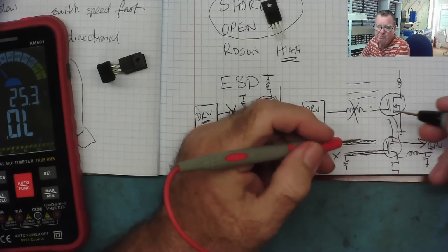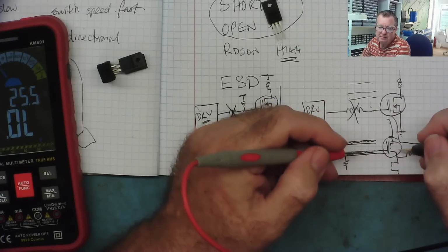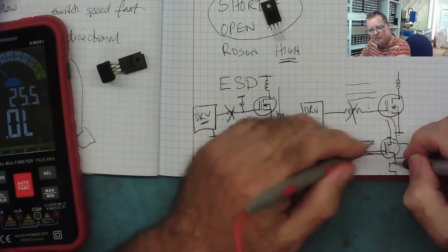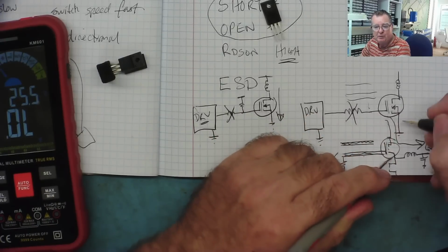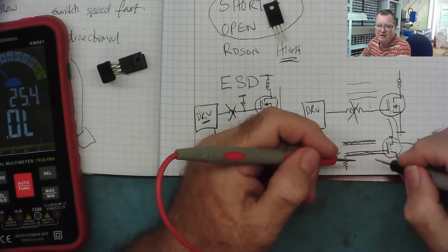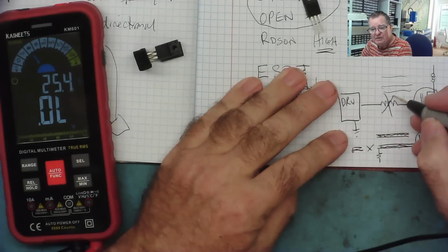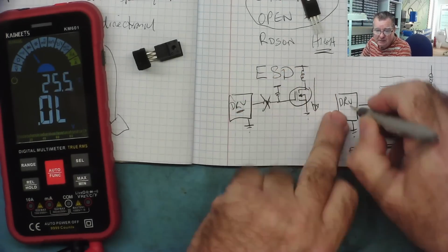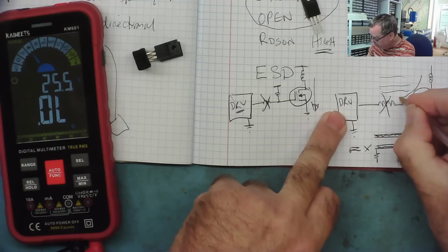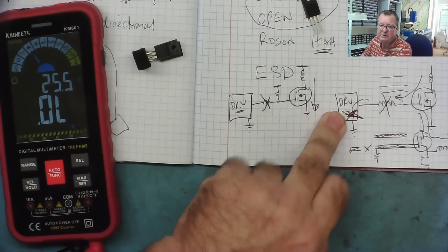And this is so reliable, it's something you should test. So when you've changed your MOSFET, your shorted one, try what I've said. Try to switch it on by applying voltage to the gate. And remember, P channel is the other way round. And make sure that you can't switch it on that way. If you can switch it on that way, find the gate resistor. And if that's okay, have a look what's wrong with the driver, because it may be that when this went short, it didn't blow the resistor, but it blew this. And this is now open circuit inside.